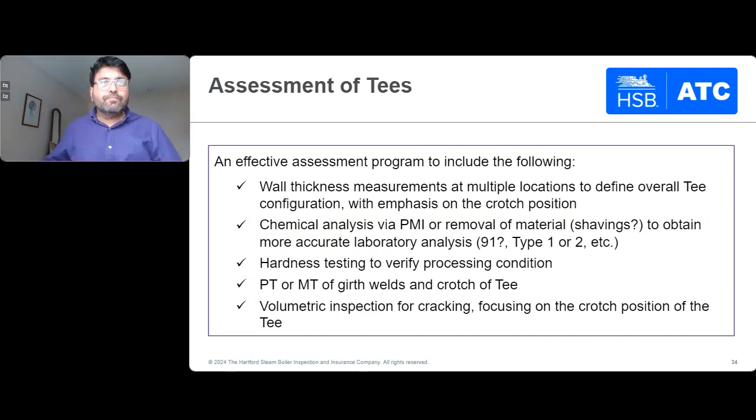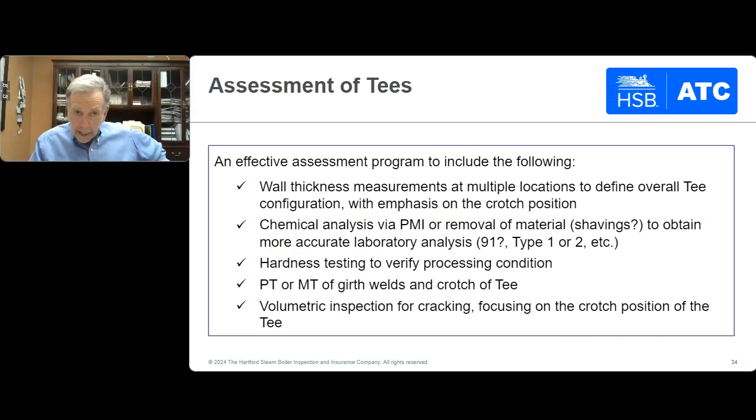Yeah, thank you, Jay. Before I get into the issues associated with assessment of the T's, I did want to mention a couple of other things that I failed to mention earlier. Obviously, when you see failures at a component like this in a piping system, one of the first things that would come to mind is that the piping system isn't properly supported and these T's are too heavily loaded.